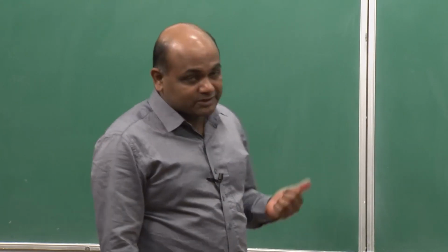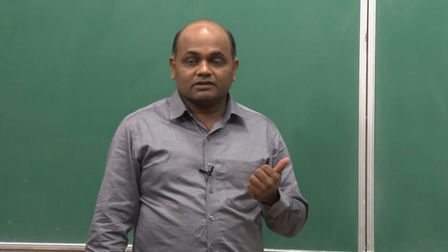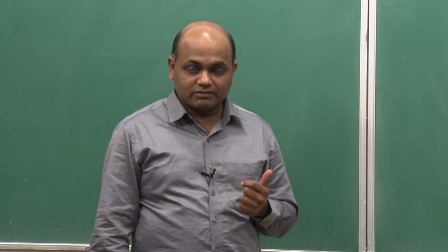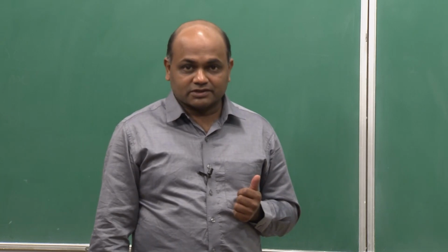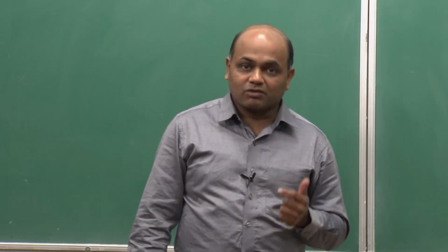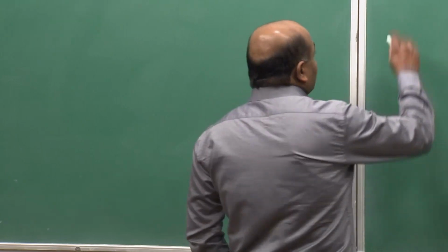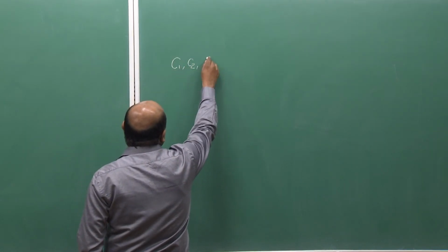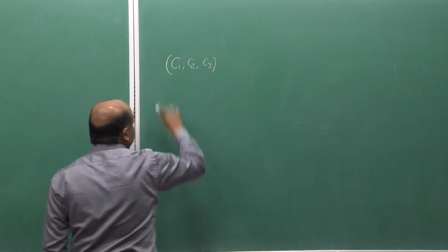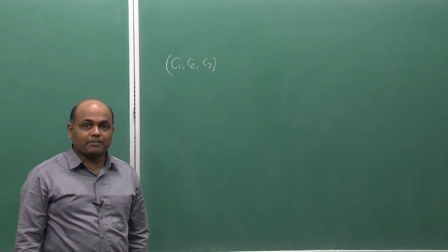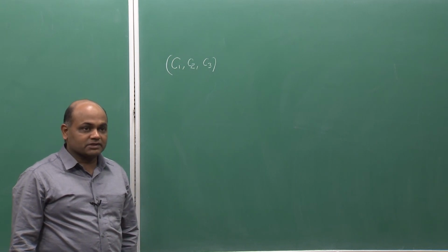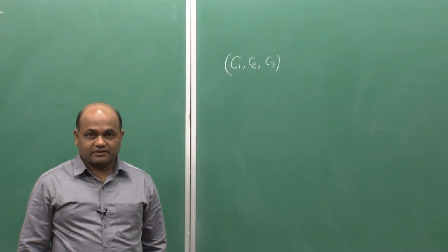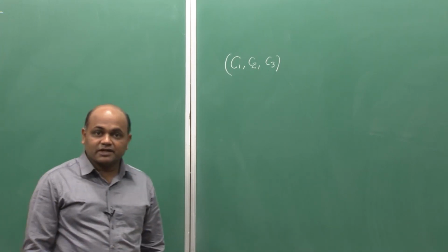I will explain this with the help of a quaternary system, and then how we can extend it to higher order systems. When I consider a quaternary system, I need 3 independent concentration variables to define one quaternary composition. So, if I plot a particular composition, I need a 3D composition space. The fourth one is of course dependent.